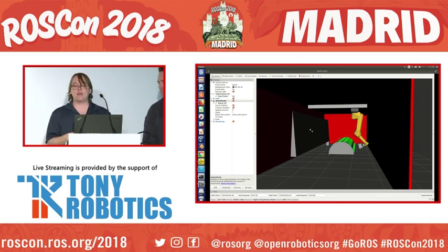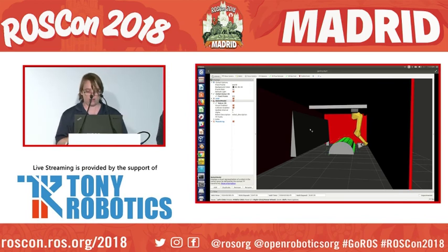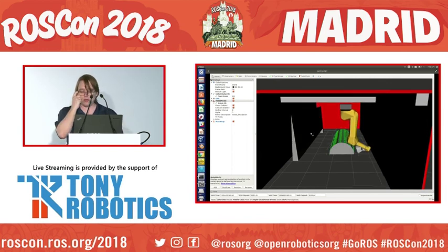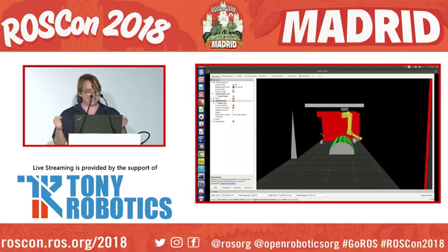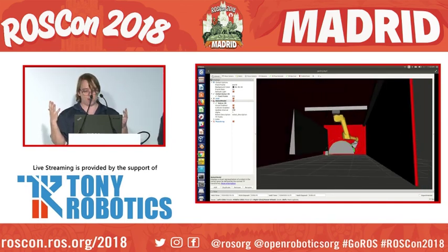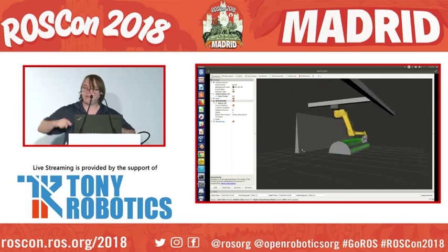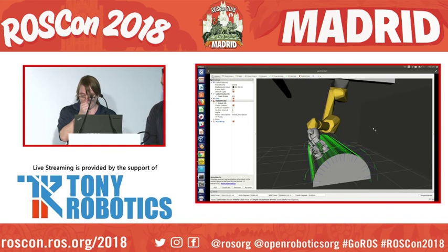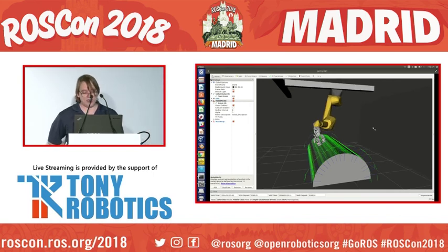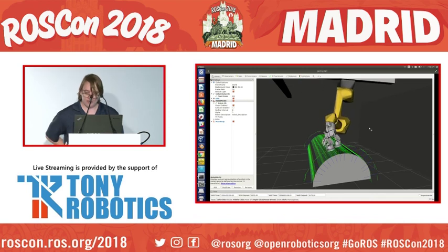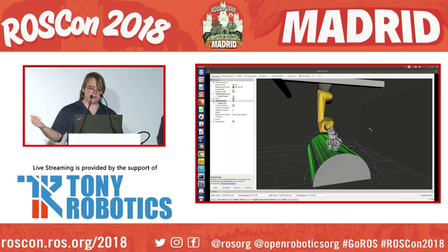In practice, what it means is that we can be extremely robust in the sorts of things that we do. And just to illustrate another, perhaps not super exciting example, this is a 9-degree of freedom system. It's 2 degrees of freedom on a rail, 6 degrees of freedom on the robot, and then a free rotation at the bottom. And it solves fairly quickly. We're talking 3 or 4 seconds, and it produces paths that are pretty reasonable. So anyway, you get the idea. It just keeps going.